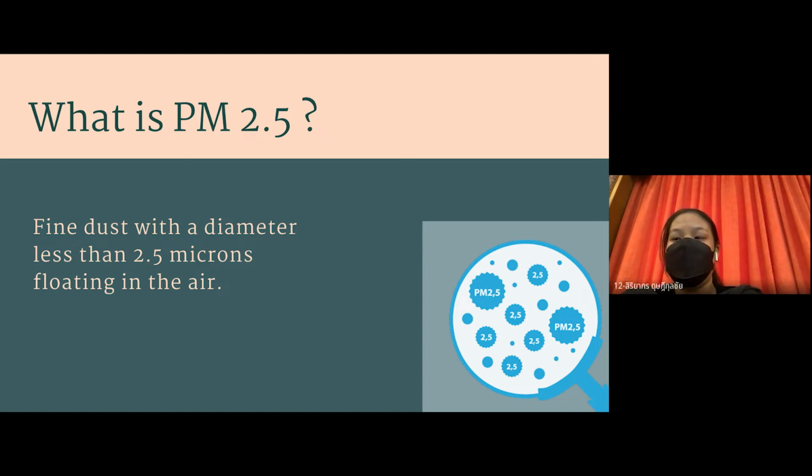measure air pollution concentrations. However, previous studies have pointed out the inconsistency between low-cost sensors and high-quality regulatory instruments. Low-cost observations may contain uncertainties, mainly due to aerosol streams, temperature, and high relative humidity. The sensors may also indicate bias, as the models are dependent on location, hygroscopic growth, and a specific range of relative humidity. Each sensor type has distinct characteristics, and many factors affect light scattering, including particle size, shape, composition, and relative humidity. Moreover, the particle number and mass concentrations significantly increase in high relative humidity.